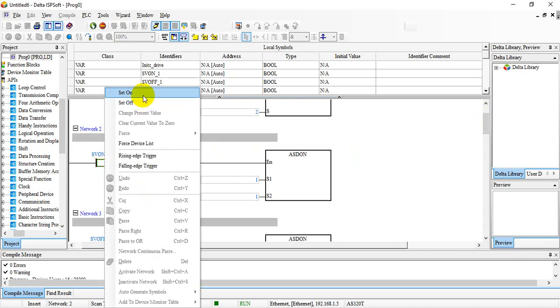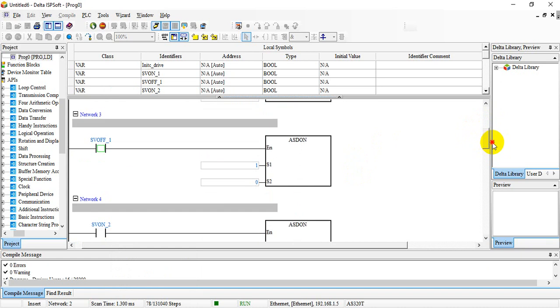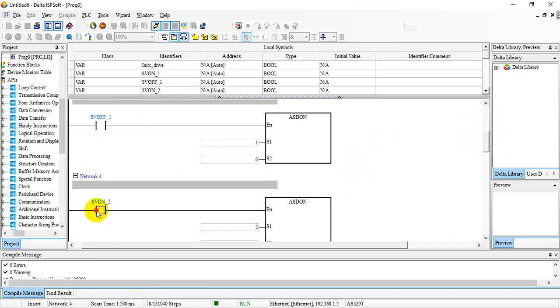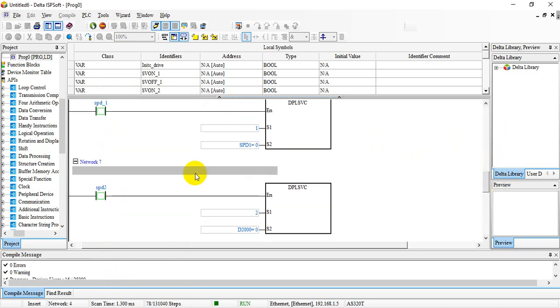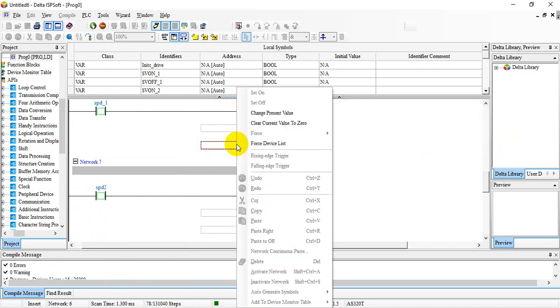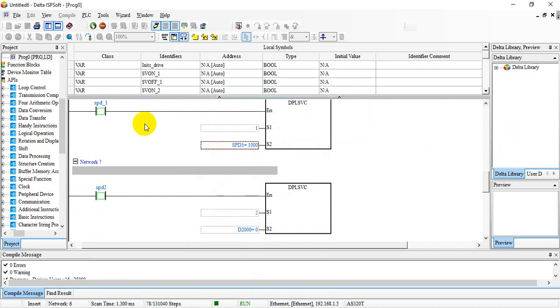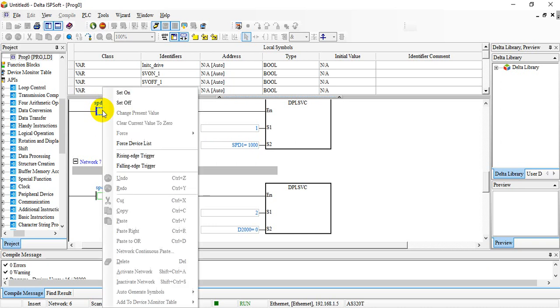Then we can do the servo arm of A6 and servo arm of second A6. After that we can set the speed. If you still remember, the unit is 0.1, so if we put 1000 here, that means it will move 100 RPM.